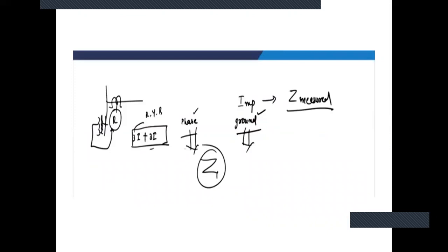Whether it is the ground relay or the phase distance relay, whenever we feed the quantities to the relay, as I have told you, a relay is connected somewhere on the secondary side, and we connect the input to the PT secondary. So the relay will receive three currents and three voltages.